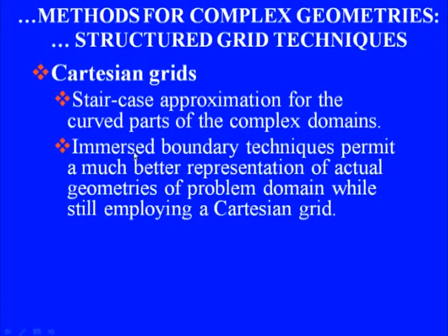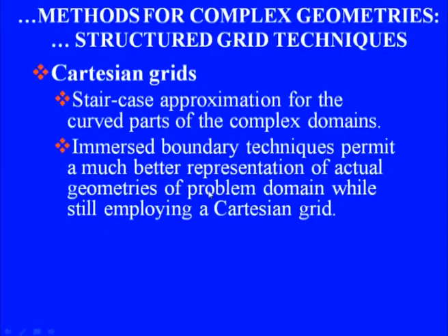These immersed boundary techniques are based on Cartesian grids, but they permit a much better representation of the actual geometry of the problem. We can have almost exact representation of the problem geometry using what we call immersed interface techniques. So, though our CFD formulation is based on a Cartesian grid, we will introduce certain features or certain forcing terms which can give the effect of the presence of curved geometric features exactly the way they were. So, programming is a bit complicated, but then